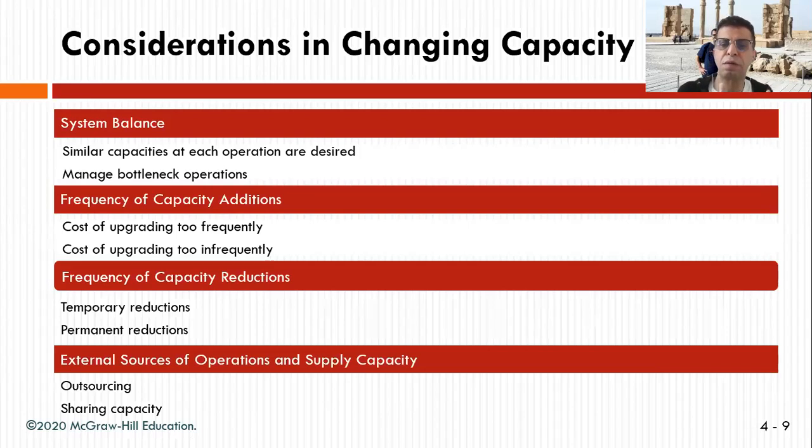And sometimes the first one makes 100 and this one makes 50. So there is a bottleneck effect on the operation. To solve this problem, you probably need a second machine, or you need the first machine to produce less, or, for example, have the second machine run 24 hours while this one operates 12 hours a day shift.